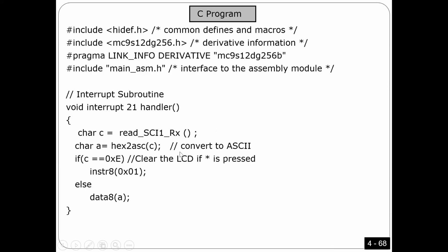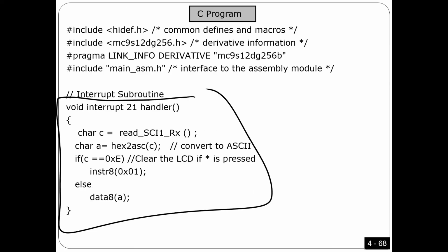For the receiver, this is the interrupt here. Every time the receiver receives a byte and the byte is ready for you, this interrupt subroutine is triggered. So all you have to do is read this value and that's it. How can you read this value, guys? As you see here, we have another function, and you just read using this function.